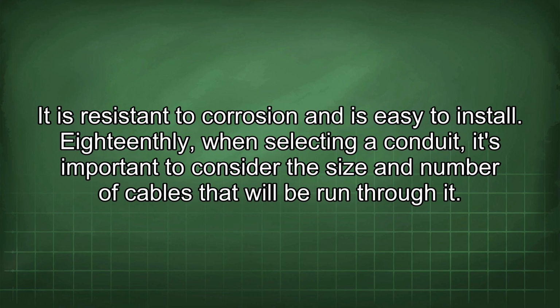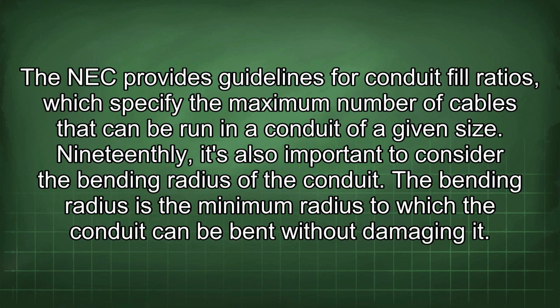18thly, when selecting a conduit, it's important to consider the size and number of cables that will be run through it. The NEC provides guidelines for conduit fill ratios, which specify the maximum number of cables that can be run in a conduit of a given size.